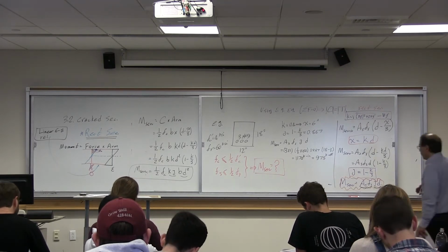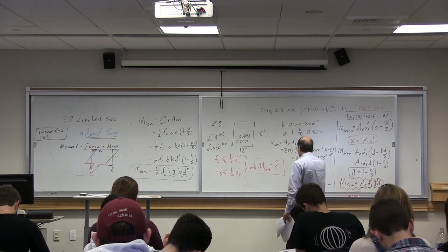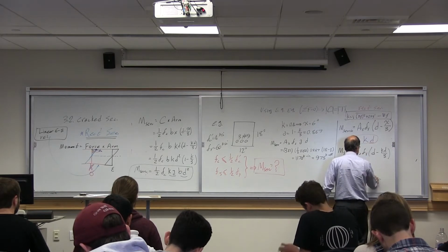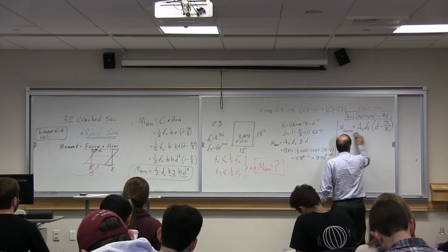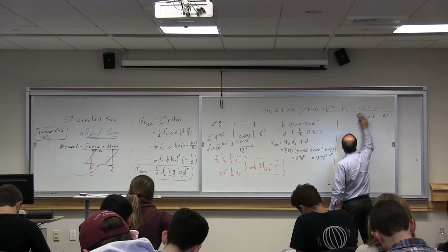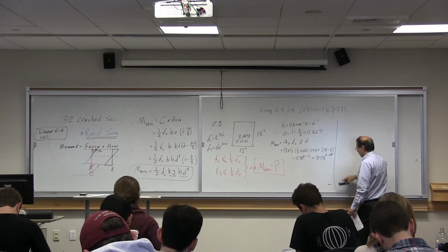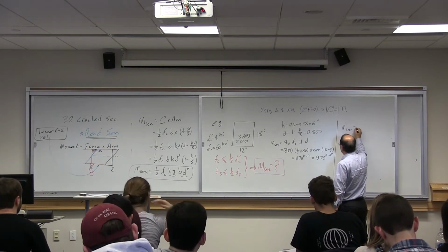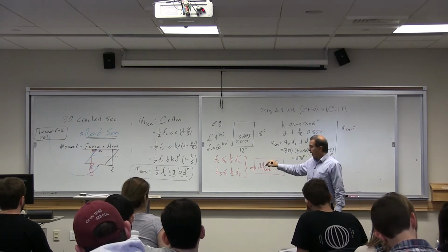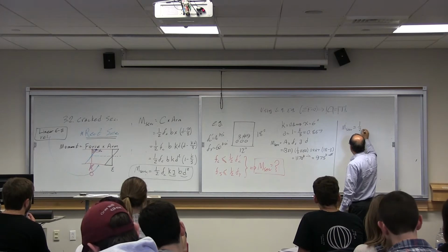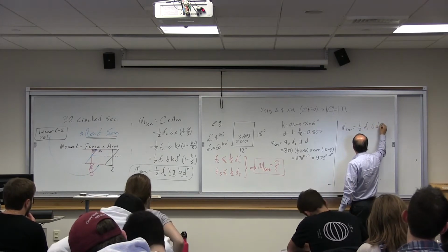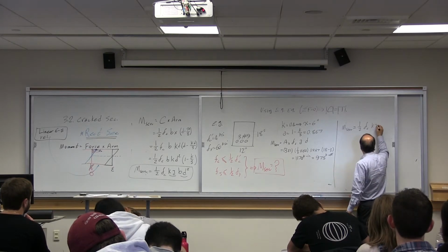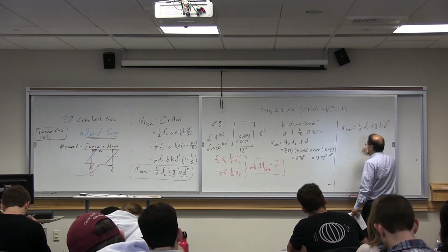At the same time, we want to make sure that the stress in concrete is also less than 1/2 of F prime C. Therefore, M service is equal to 1/2 of Fc JK or KJ b d squared.